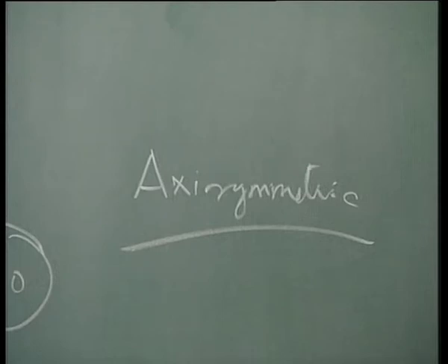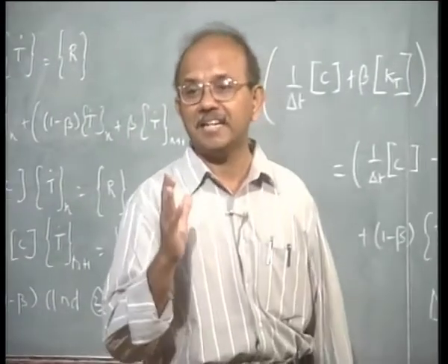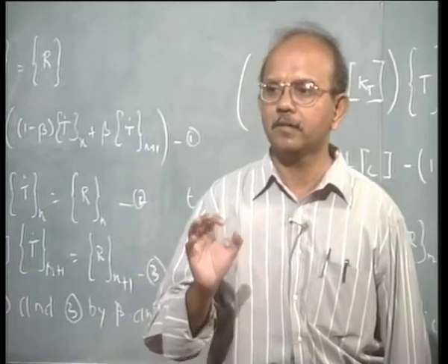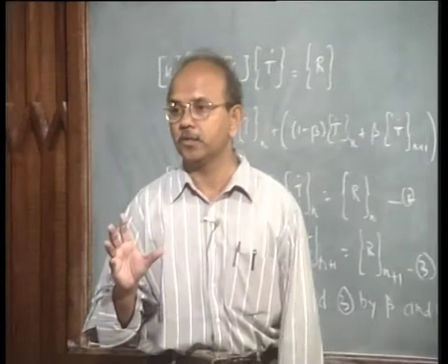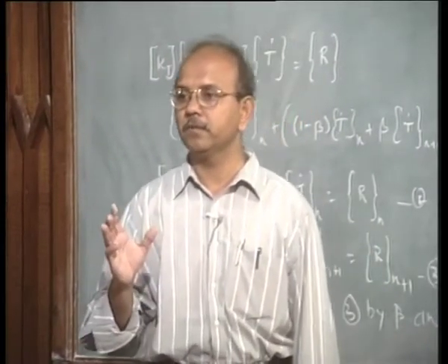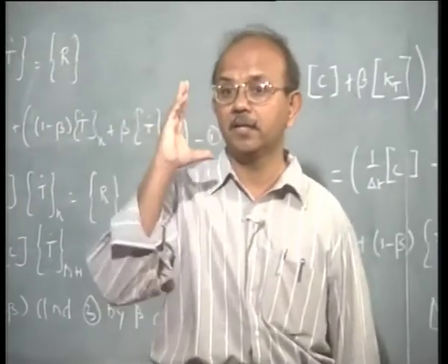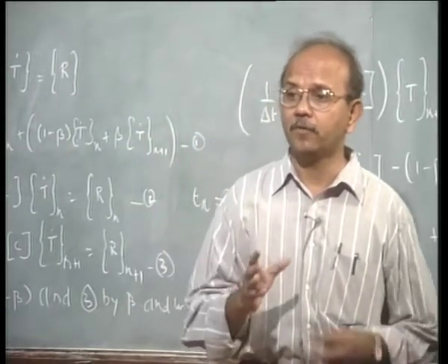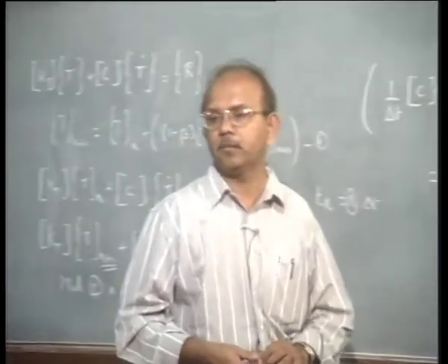The procedure is exactly the same, or the set of equations that you are going to deal with is exactly the same as that of plane strain and plane stress, but there is one r there, the radius, which comes into the picture. Remember that we had looked at it when we discussed the strain displacement matrix early in one of the earlier classes, but we have not looked at it again after we had put down the isoparametric element formulation.